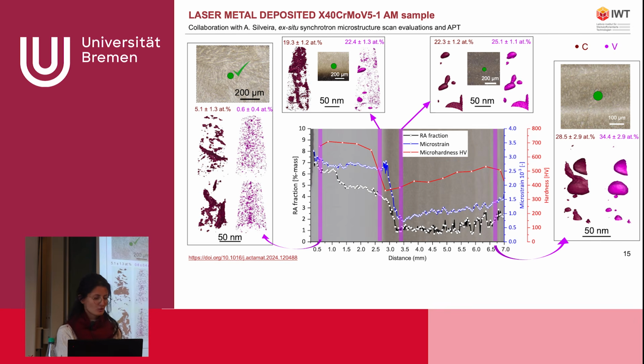So this was an illustration of the typical information that we can have with atom probe tomography, and of course, we can apply this technique to all metallic samples. There will always be some information about what type of precipitates we have, which will evaporate at a different field as compared with the matrix. This may cause some artifacts, of course, but if we know that this is happening, we can correct this.